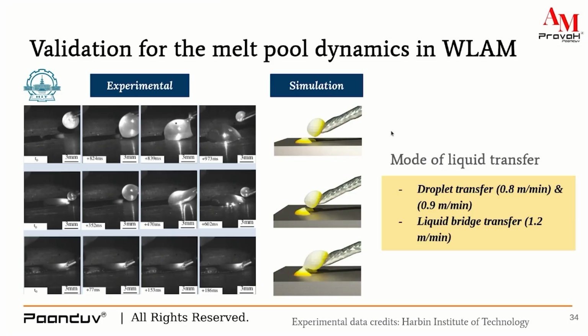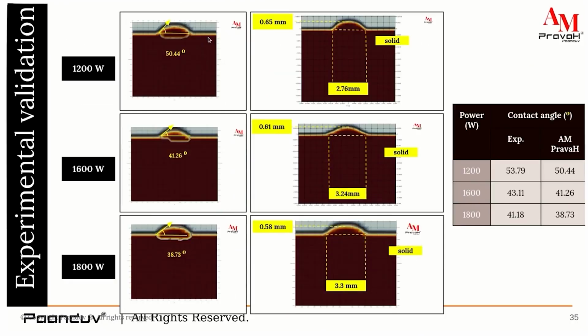Now, this is a case study that we have performed. The alloy here is SS316L. This data is coming from one of my colleagues, and the melt pool dynamics, melt pool shapes are quantified, and corresponding to that, we have created a single bead analysis for melt pool for microstructure evolution. Now we have this single bead information. With this single bead information, we have extended further to multi-layer, multi-track systems. So now we have 5-layer, 4-track systems in the microstructure analysis.